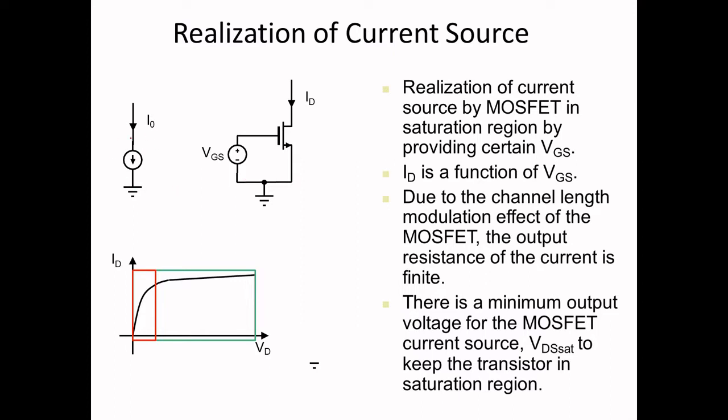So this is a normal current source circuit that we expect. Now I'll take a MOSFET. In the MOSFET, this is your gate, this is your drain and source, right? What is the basic equation for the MOSFET? That is the master equation for the drain current: ID equal to Kn (VGS minus VTN) whole square. Here, this drain current is dependent on this VGS.